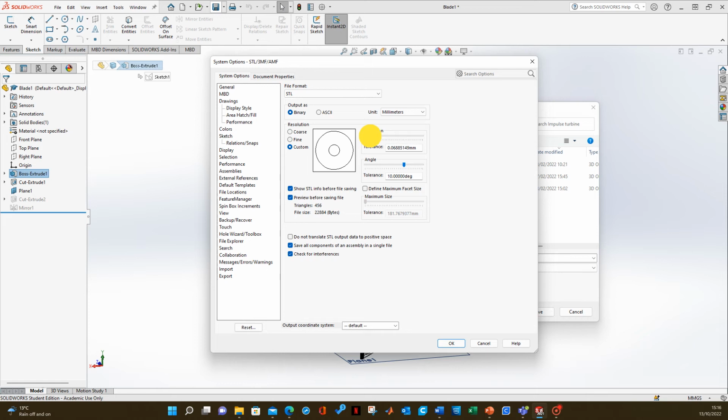You can play around with this when you create your mesh. When you bring it into the 3D printer, you'll see how accurately curves have printed and if they have flat lines on them, a series of straight lines rather than a nice even circle. So you can probably go with something like this. I think that looks about right without creating the mesh too big.